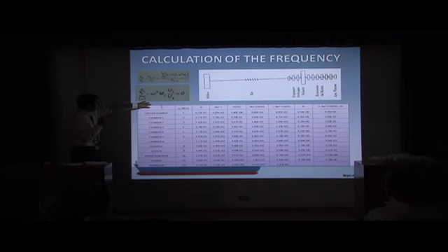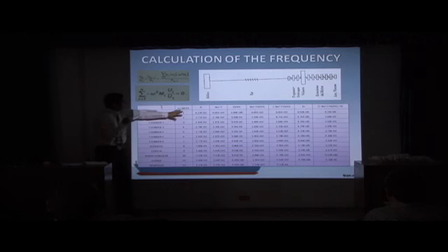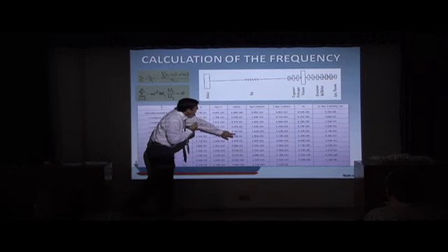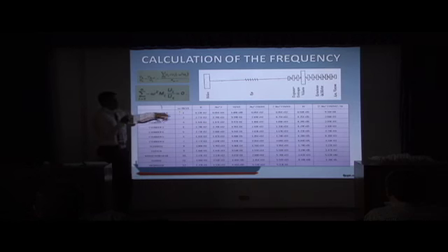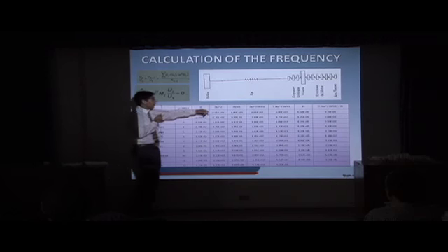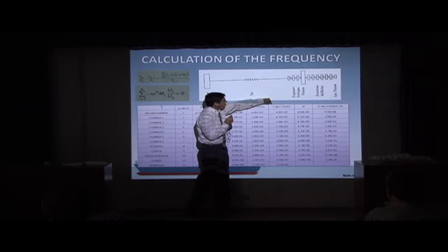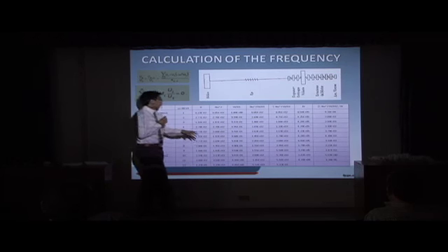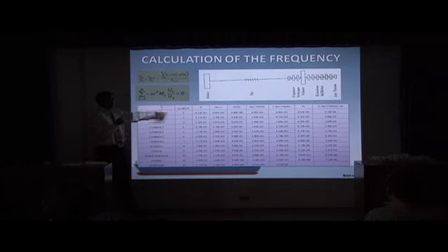In this part, we have all the elements in the system, and here is the inertia. This is the modal shape. This is the value of the frequency. This method is iterative because we change the frequencies. Here is the check equation. When this value is approximately 0, we say that this frequency is a natural frequency.